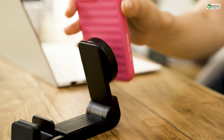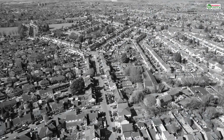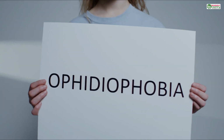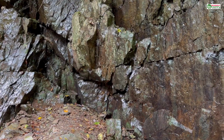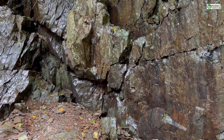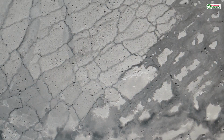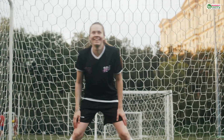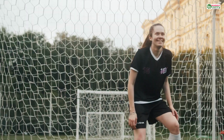Remember, every time a support touches your model, it leaves a mark. It's unavoidable. The surface where the support connects will never be as smooth and perfect as the other surfaces of the print. It will be a little rougher, a little less defined. This is the price of defying gravity. So your goal is always to minimize these contact points, to hide them on surfaces that aren't aesthetically important, or to get rid of them entirely through clever orientation.